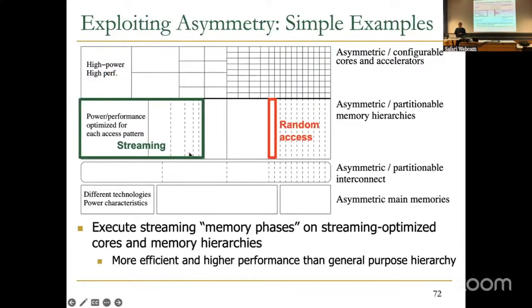You can design the memory hierarchy differently for streaming versus random access. We've kind of seen examples of this with prefetchers, etc. But I think there needs to be more over here. If you remember, for example, stream buffers, they were getting rid of the caches, right? Earlier. It's good to re-examine some of these things. Today we have these huge caches, and people don't re-examine some of these fundamental decisions, in my opinion. Huge caches are easy to build and easy to put. If you have area, let's waste area, let's put it over there. Let's forget about all of the costs of it. Whereas if you're streaming, those caches are useless, and they actually hurt performance. And we don't have a way of actually streaming easily into the processor today.